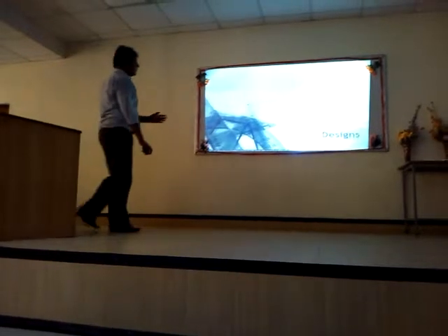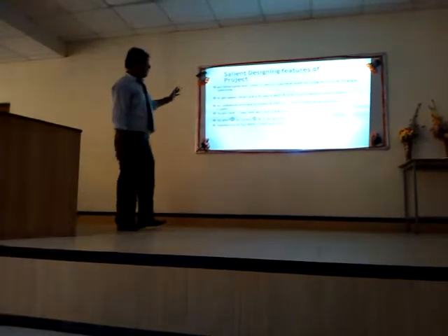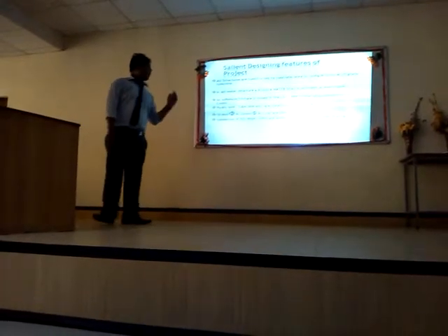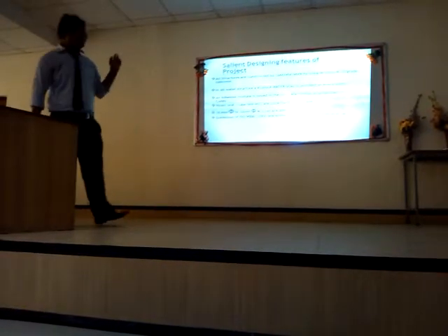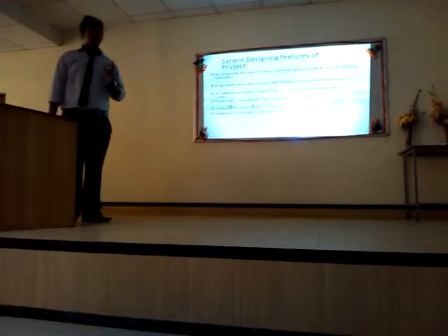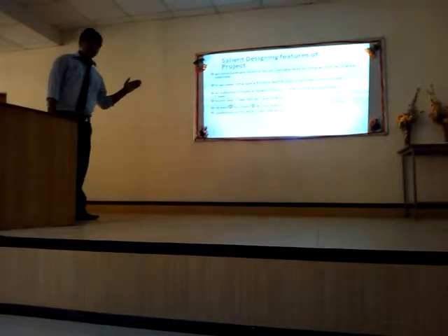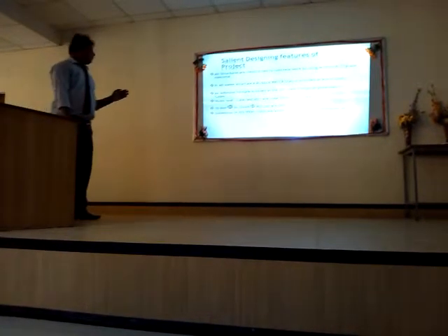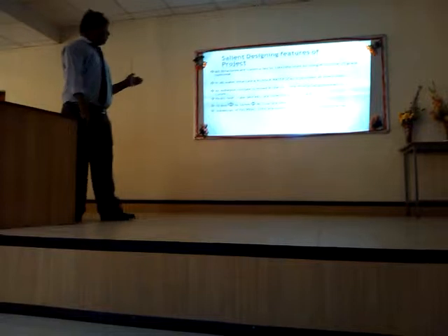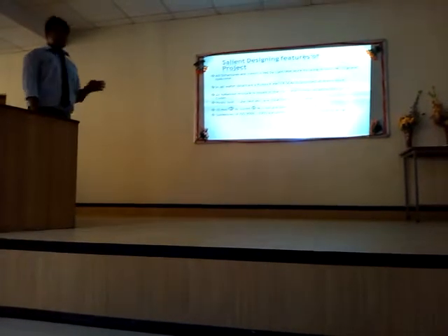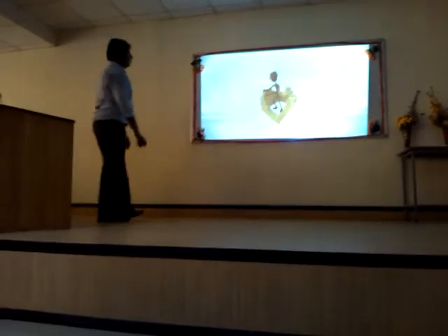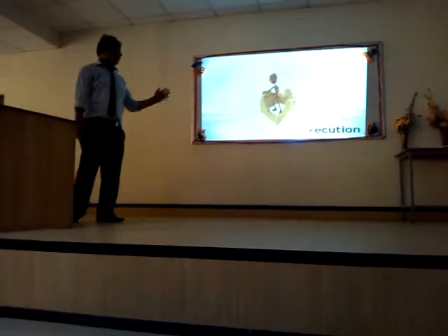Now the next portion is the design portion. In the design portion, there are some salient features which have been kept in mind while constructing the project. All structures are made from M25 and M35 grade concrete. In all water structures, a double seal is provided, and in every water structure a hydro test and tube test is done. 10 to 32 mm diameter bars have been used in the construction, and ISO 9000 guidelines are satisfied during the execution.